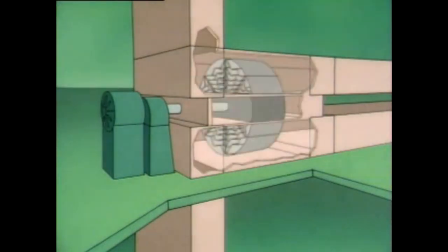In some boilers, the air supplied to the combustion area is preheated. Preheating the air raises its temperature closer to the point where ignition occurs. This, in turn, helps to ensure efficient and complete combustion. One way to heat the air flowing into a boiler is with a rotary air heater, or preheater.